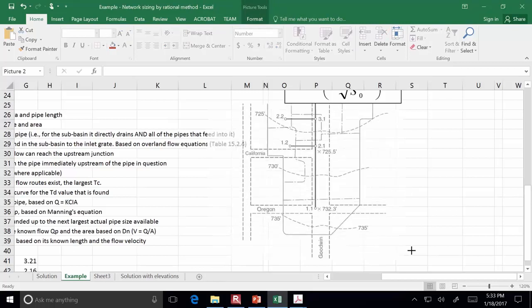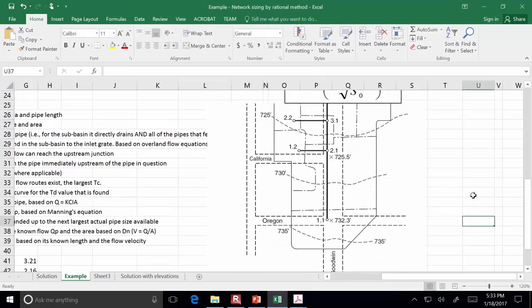All right. Think about how the water is getting into pipe C. The water can get into pipe C from three different locations. It can get in that pipe through this inlet, through that one, or this one. So we have to say, what's the longest travel time that it could take? Maybe a raindrop falls here in this corner, and it flows over the surface, and then it gets in the pipe, and now it's about to enter pipe C. So how long did it take? And we could measure that in minutes.